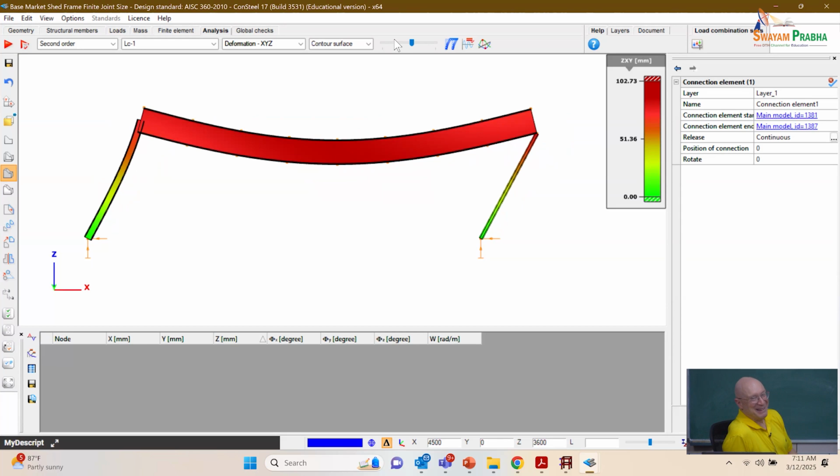The load is causing an extra moment because it's at a... Okay, all right. Like a P-delta moment? Yeah. So notice by doing this, now my leaning column, this HSS column, is shorter, right? The shorter I make that column with the same delta, the bigger P-delta effect. Same delta, short length, bigger P-delta effect, right?